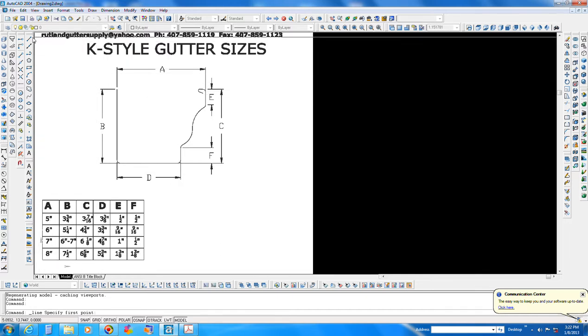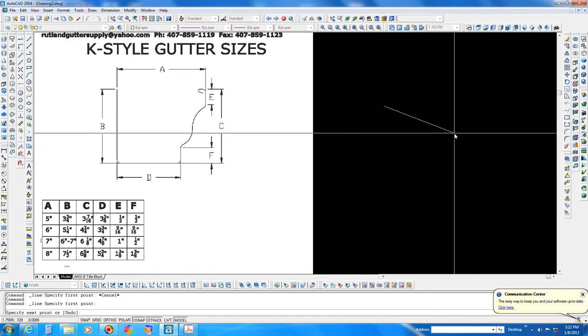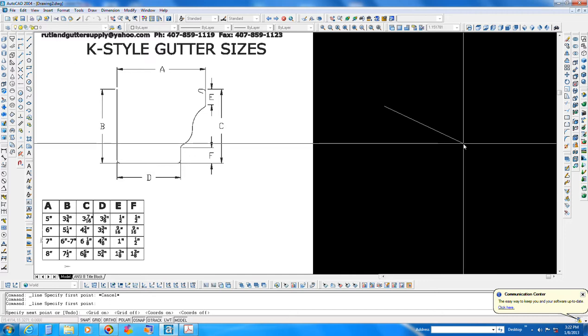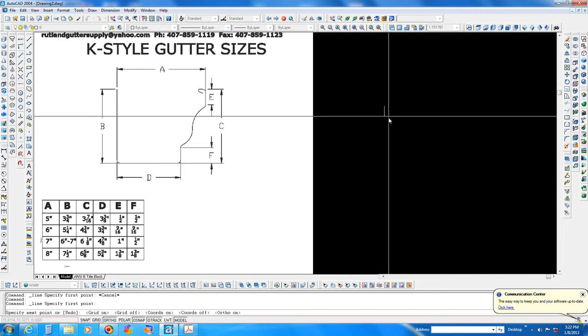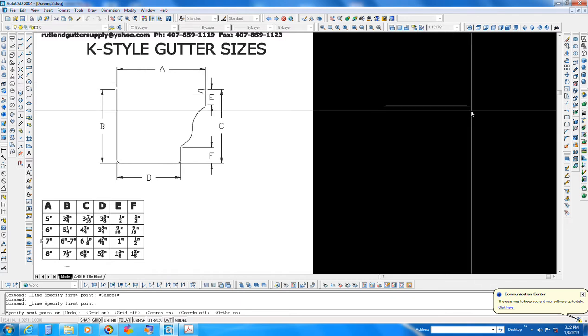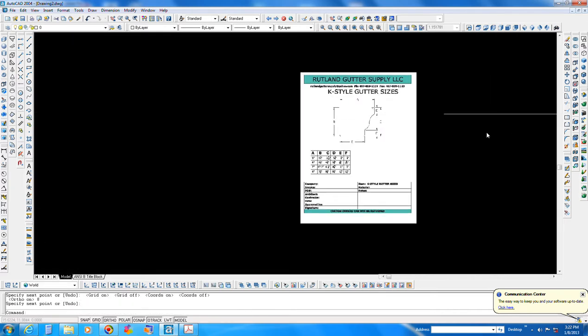That's an 8-inch span. So we're just going to pick the line command up here and draw a line. Right now I'm in a polar coordinate. If I hit F8, I'm sorry, that's F7, I'm not looking at my keyboard. If I hit F8, it'll draw it in a rectangular array. So let's pick out here, and we're going to come across 8 inches. We'll specify 8. So we just type in the number 8 on the keypad.